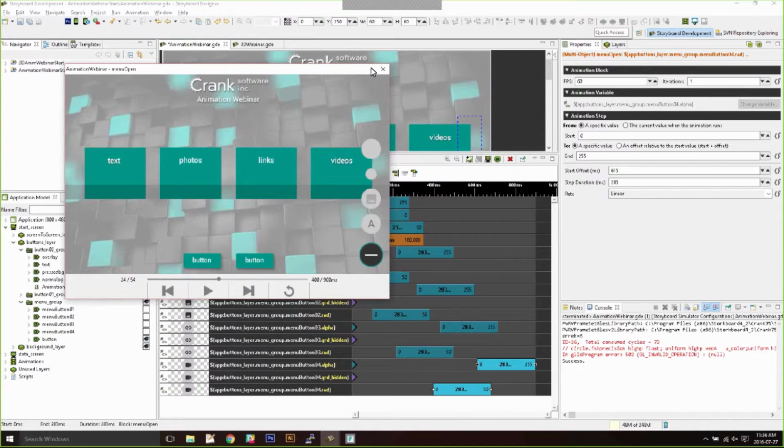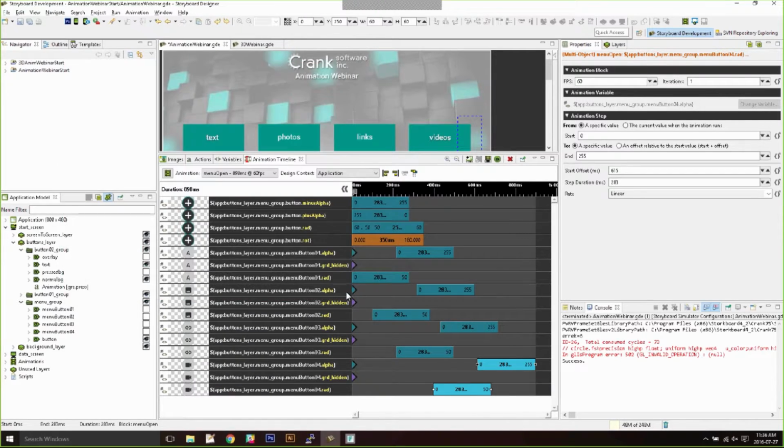What I'll want to do is go back into my animation timeline and initialize these variables to make sure that this doesn't happen. So I can just close this out, and by double-clicking, again, you can add in any step between two animation steps or between the beginning and the animation step next to it. This will have an animation going from the previous animation's value to the start of the next animation's value. I will double-click in, and it will add in a filled animation. And I can just double-click in these areas that I want the animation to be in.